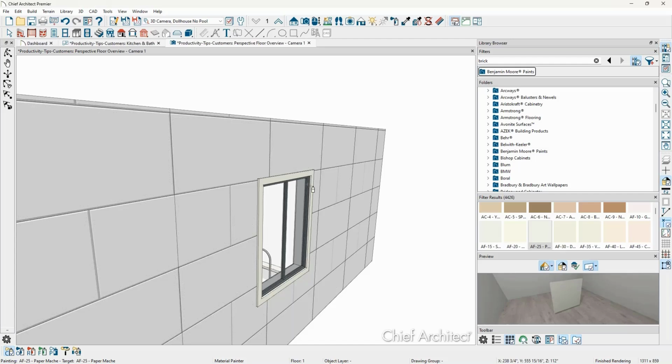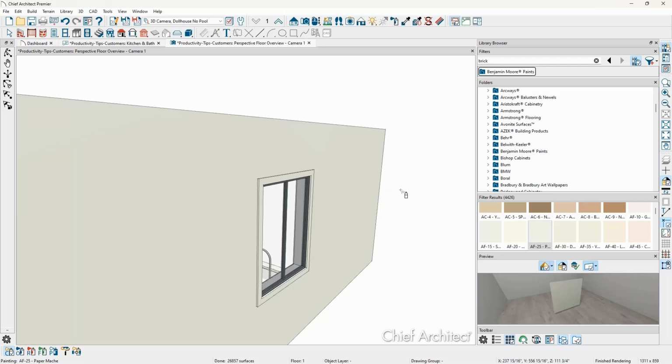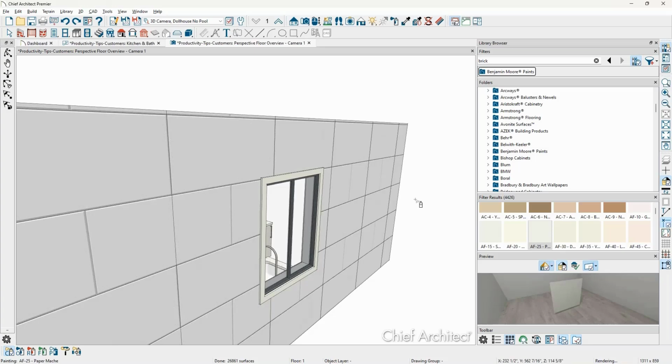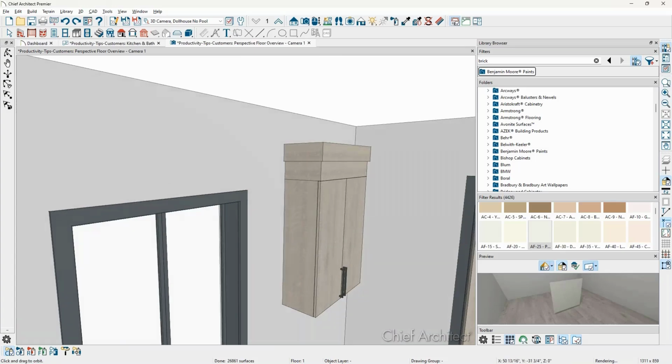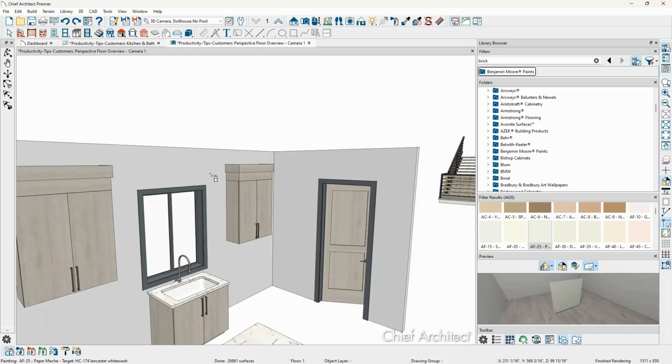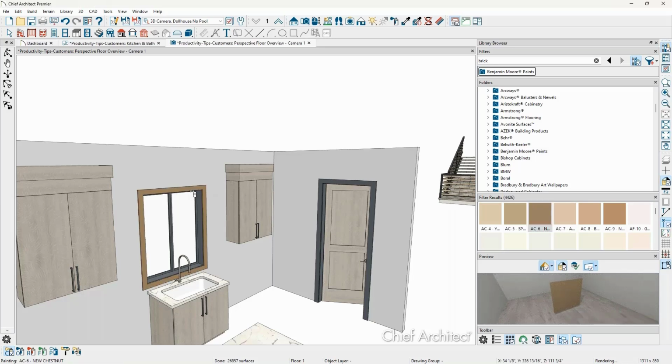So what I do is I hold the Alt key down and the middle mouse button, Alt key, middle mouse button, and that allows me to rotate. I'll use my wheel to zoom in and zoom out, and I'm still in the paint mode, and that allows me to paint something. I see that we have to press the Alt key and then turn around.